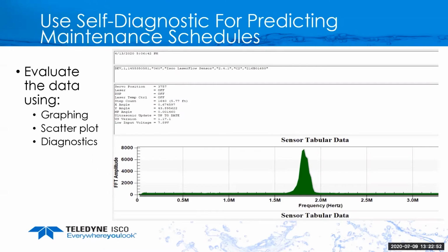One thing that should be noted, especially with the laser, is that it reads the absolute velocity where it looks. And what I mean by that is if your velocity profile is shifted to the side a little bit, the water's coming around a curve, whatever, it could potentially read low if it's not seeing the peak. It's almost impossible for it to read high. And what we're learning over time now is it will read higher flow than a lot of people had anticipated. And that just is because it is actually seeing more accurately what the velocity is in that channel.